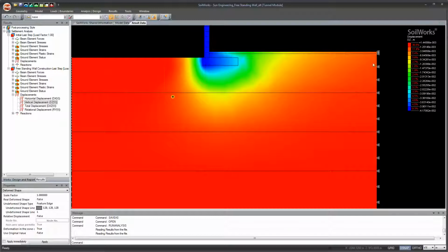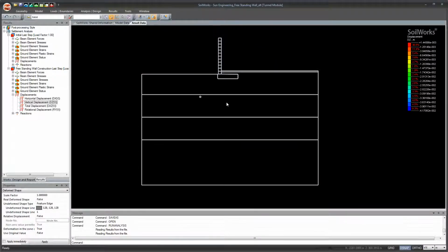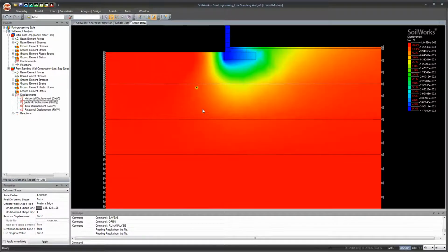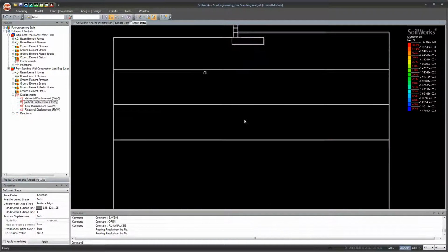And if you go to the legend here, it shows the displacement, and this is in meters. So as you can see, the further away you get from the base here, the less displacement is made on the soil. But once again, this could change drastically depending on different soil layer properties at your site in California, as well as any additional loadings placed on either side of the wall. But just for this case in particular, the pipe is virtually unaffected by the construction of your wall.